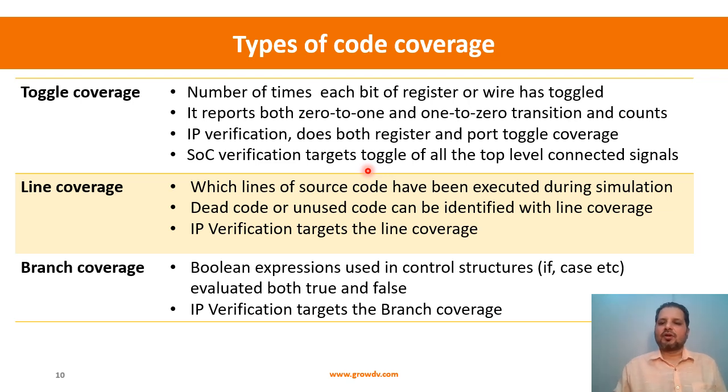That is your primary focus when you go to SOC verification, because, let's say I have a UART, I have a SPI, I have a USB, I have PCIe. Each of these IPs has been either pre-verified or bought from some IP vendor. So from a verification team point of view, it's a pre-verified IP. Right now, when we do the SOC, what we are ultimately trying to do is connect all of these blocks together. So the only additional logic that's really coming in is the way we have connected these things together and how we are generating the clocks and resets, and then some low power management. So there's only a specific part of new functionality that comes in as a part of SOC. Rest of it is pre-verified functionality.